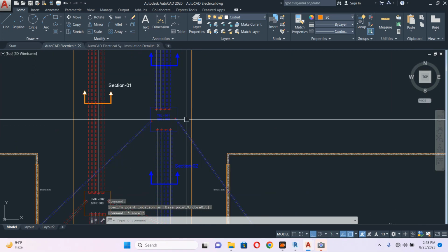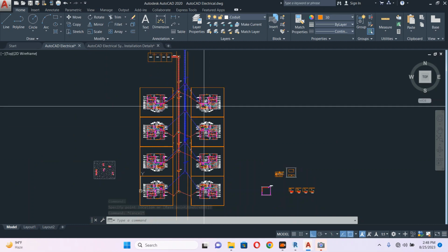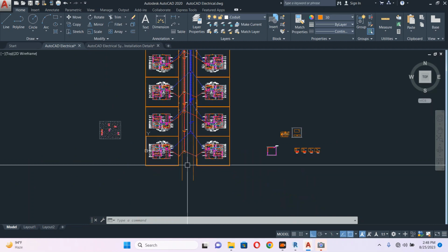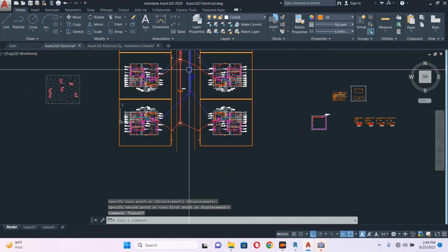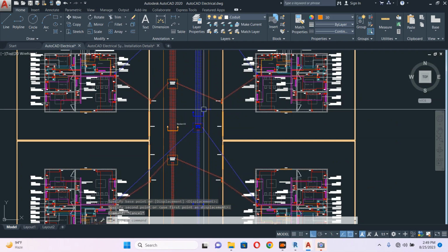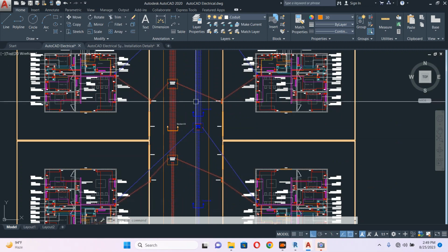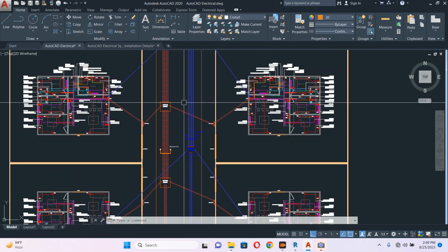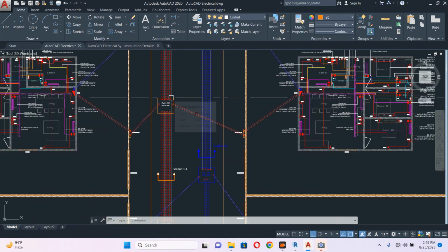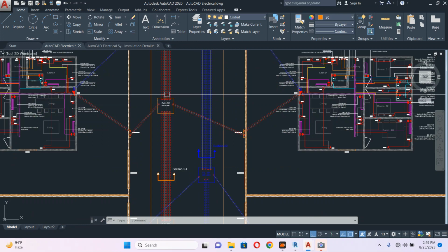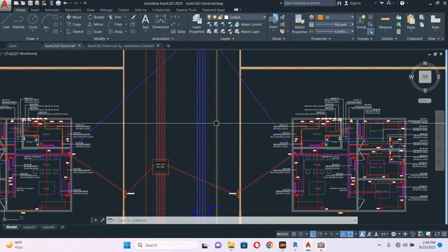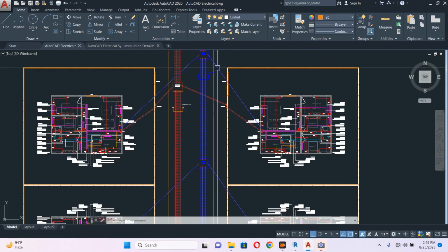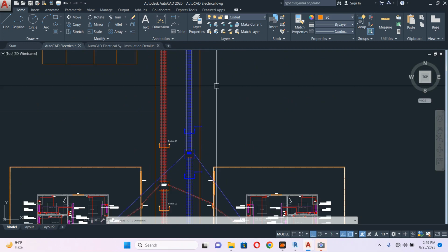So this one I think okay. See, this is how we are working for the electrical. So what else will come? There will be a pipe. So pipes like drainage and water supply should be better below. Why below? If it is above level, there will be a water issue. So this one you have to coordinate with the mechanical people, and this is how it will work.